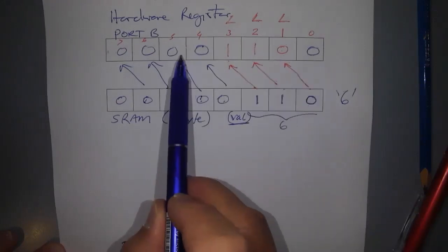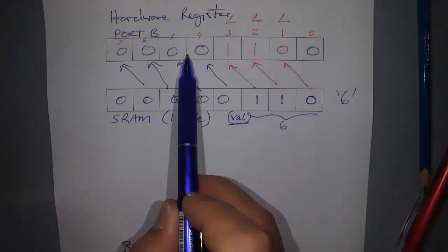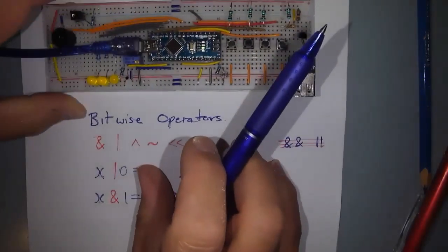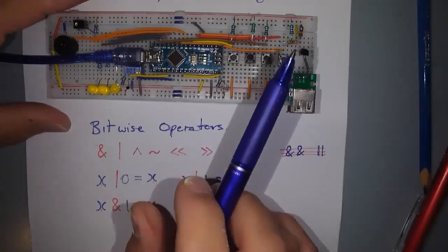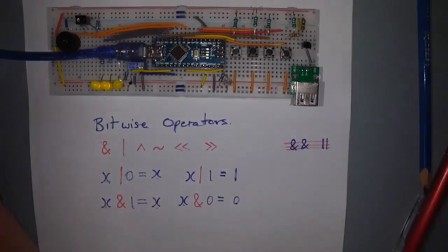But why? We're actually forcing these other things to 0, and maybe we can get away with this in this instance. Well, let's have a look at the schematic. Sorry, at the layout of the board. We've got other components on this board. They're not playing up. Well, they don't appear to be. If we have a look at our simulator here, what we've got is our 3 LEDs on B1, B2, and B3. We've got a switch on S3, which goes to B4. We've got nothing on B0, nothing on B5, and there is no B6 and 7 on an ATmega328P.